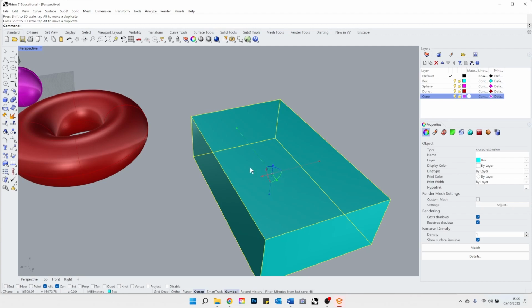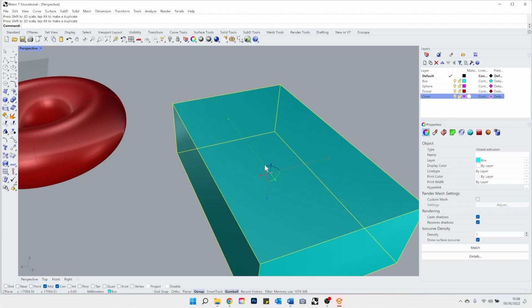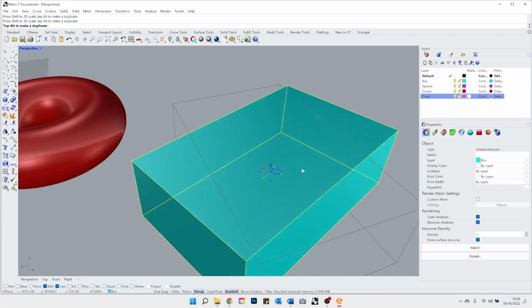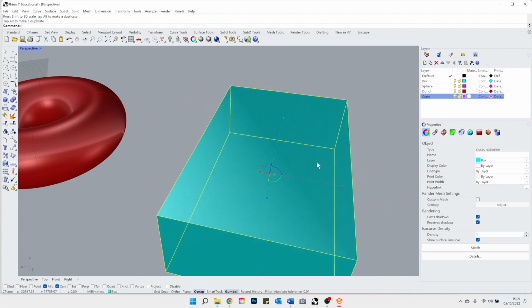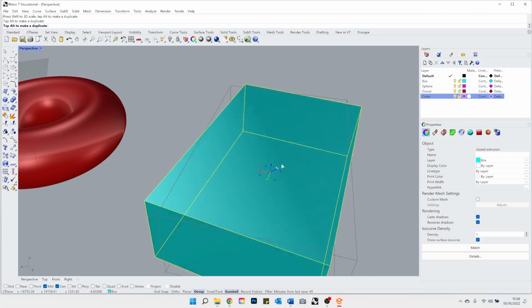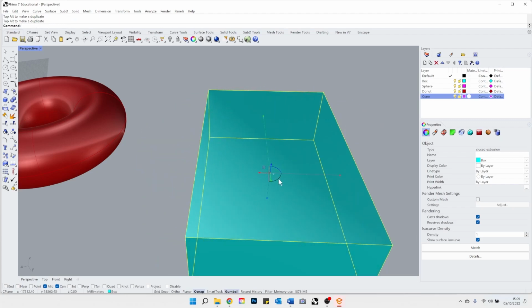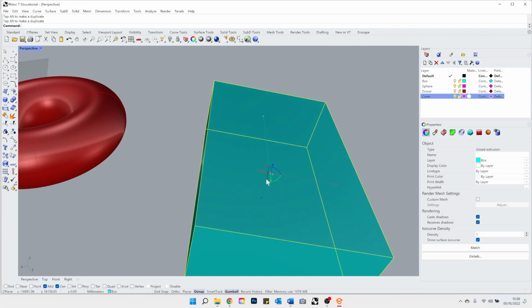Also on your Gizmo tool, you have those little arcs appearing. So blue, red, and green again. Those are your rotate tool. So instead of typing rotate and figuring out the angles that you want to rotate it to, if you only eyeball it, you can click, hold, and drag one of those arcs, and it's going to rotate it based on the axis that you have selected.